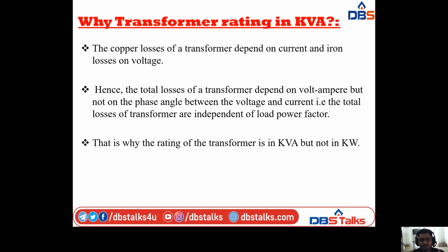So hence the total losses of the transformer depend on volt ampere, that is VA, but not on the phase angle between the voltage and current. That is, the total losses of a transformer are independent of load power factor. That's why the rating of a transformer is in kVA, but not in kilowatts. So in external exams also, they will ask this question for 2 marks.